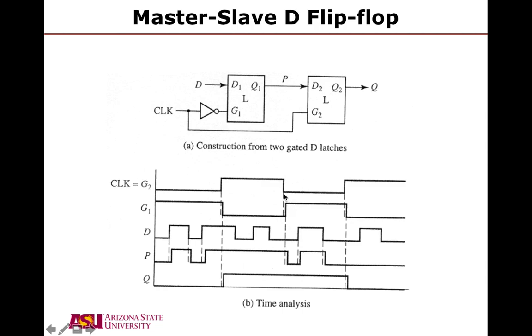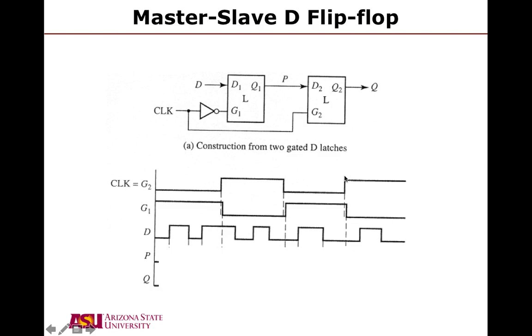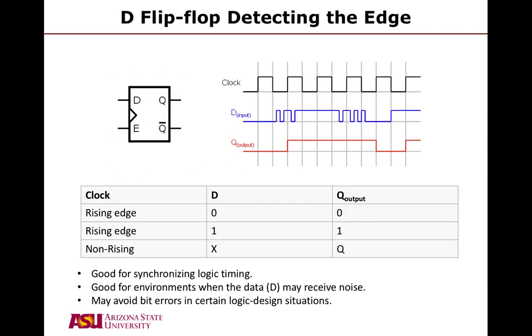And when the falling edge of the clock happens, or when the clock is in steady state, it doesn't matter, the output stays the same, high, and on the next rising edge of the clock, G2, again, it looks at what the data coming in D is. D is low, so the output with just some small delay goes low. Q goes low. So this is, again, dependent on the rising edges of the clock. It latches data on the rising edges of the clock, as shown in the truth table.